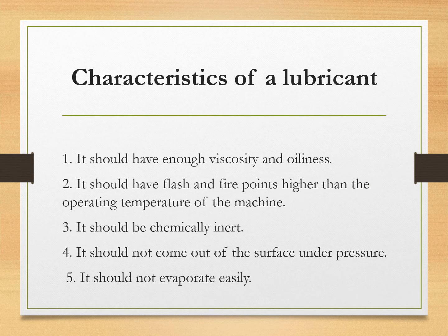When we are choosing a lubricant for a particular application, certain characteristics or properties must be satisfied by that lubricant. It should have enough viscosity and oiliness, so it should be retained on the surface. If oiliness is present, then only it will remain on the surface. If the viscosity is a little bit thicker than water, then only it is going to remain on the surface.